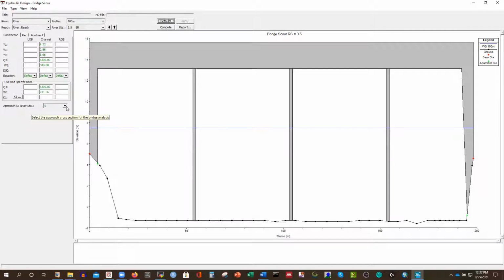So just upstream of the bridge, we have the bridge in between section number 4 and section number 3. For this one, we have to select, see, it's already there, 5. So it is not the immediate section, because this bridge section is the section number 4, even though the number is 3.5, the approach section means it is just upstream of the other section.